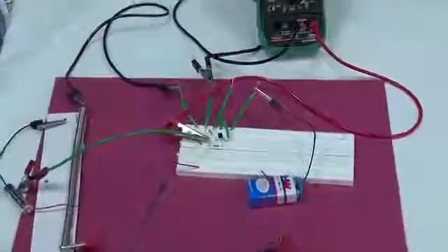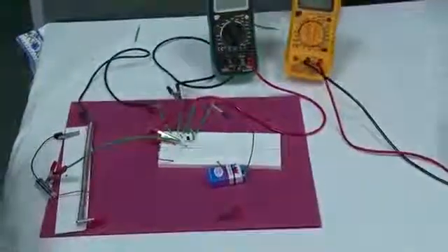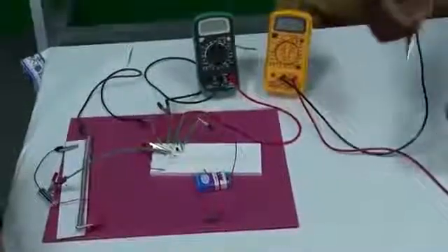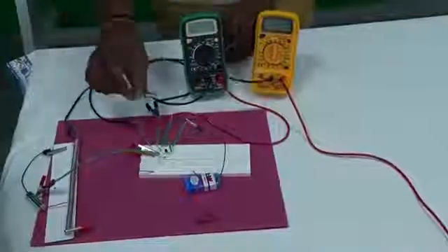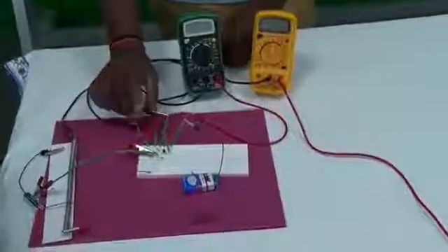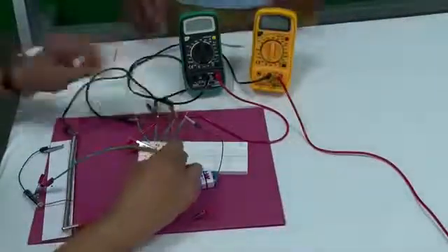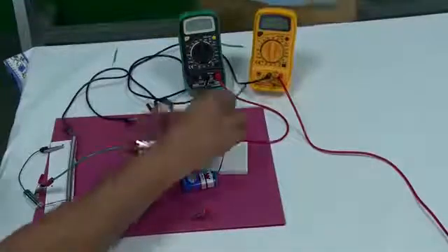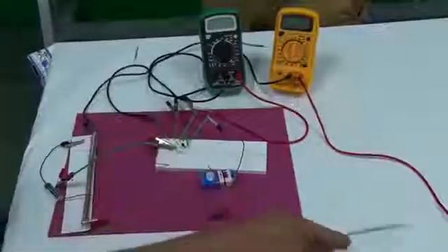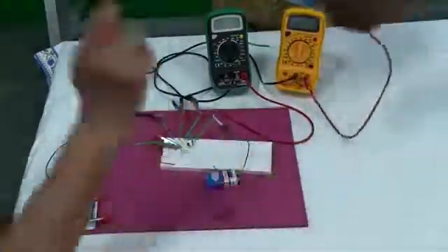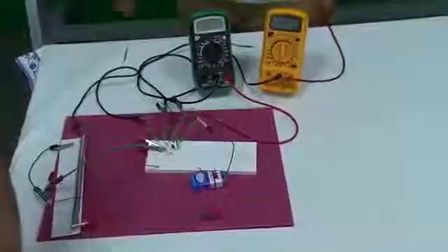Then the output side. In the output side, once again the black terminal should be grounded, 0 potential. So, see how the circuit is implemented nicely. This is also at the same potential. So, all those negative terminals, all those black leads, are joined together. Here they are all joined together. Okay. And the positive red terminal should be measuring VO, the collector. So, it has to be directly connected to the collector.